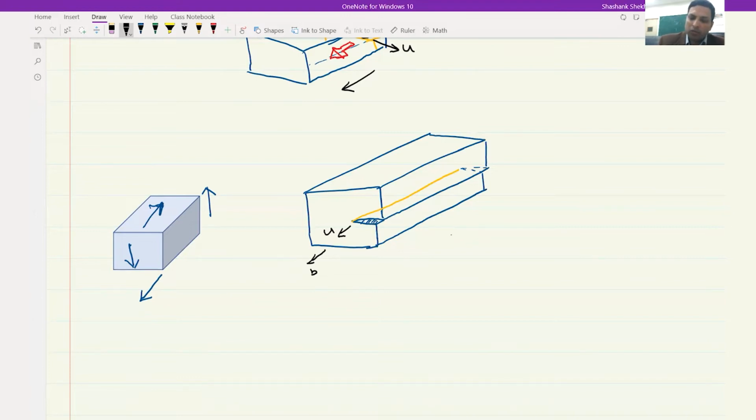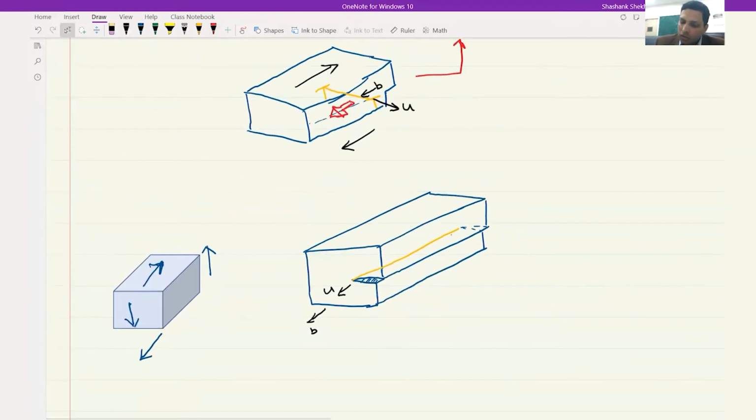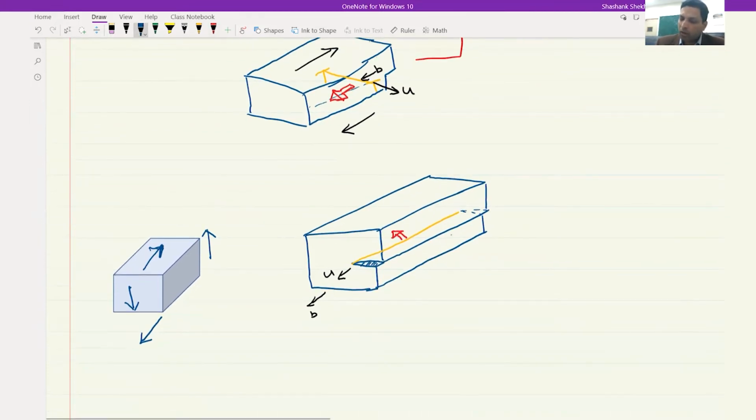So what will happen to the motion of the screw dislocation? This screw dislocation would keep moving in this direction, and eventually this would also form a step just like the above. Because you are applying shear stress like this, it will always lead to this kind of step. The other possibility is getting a step created because there is also a shear stress in the other two planes.